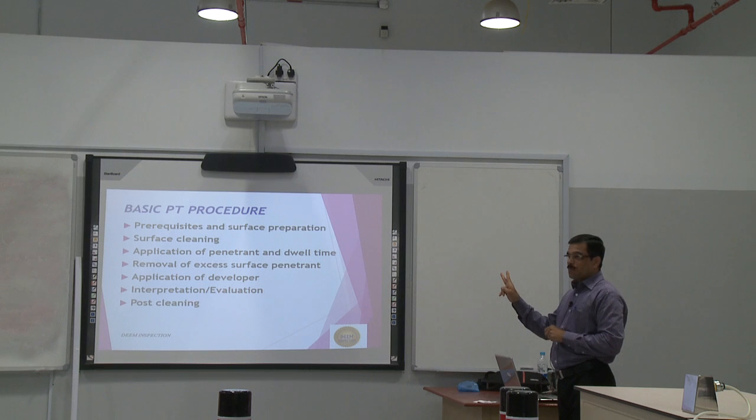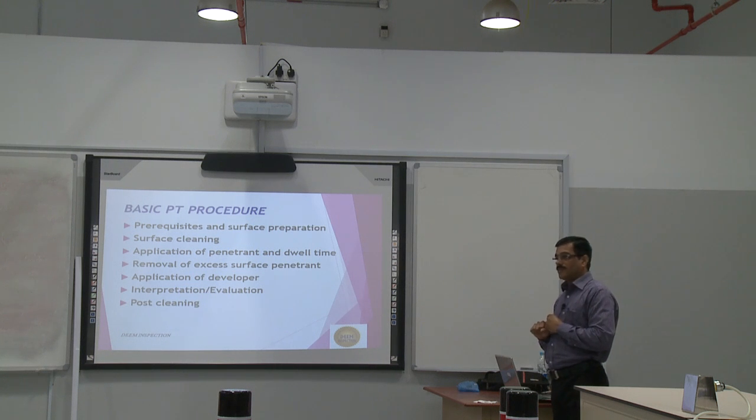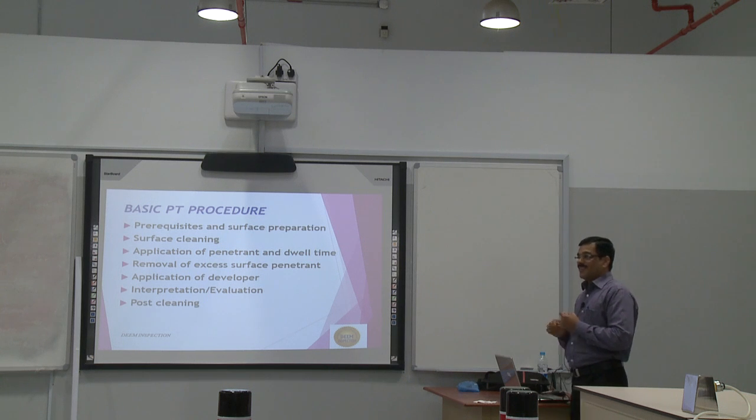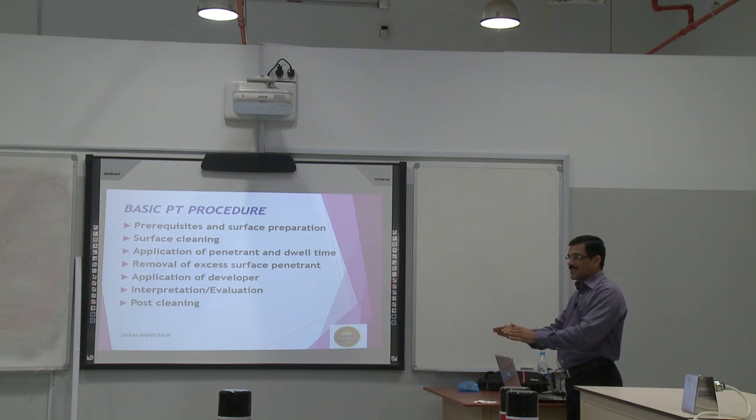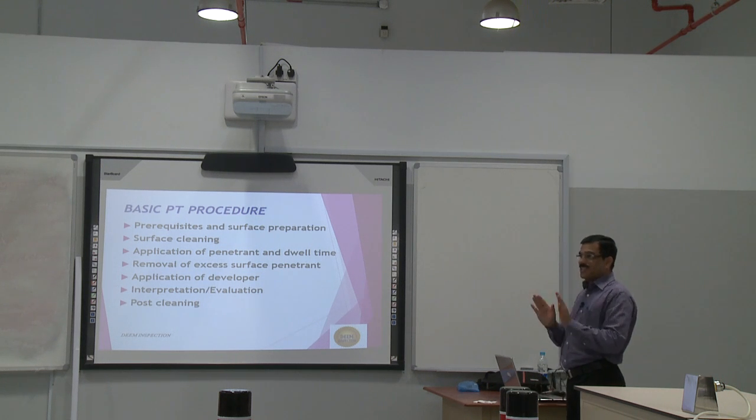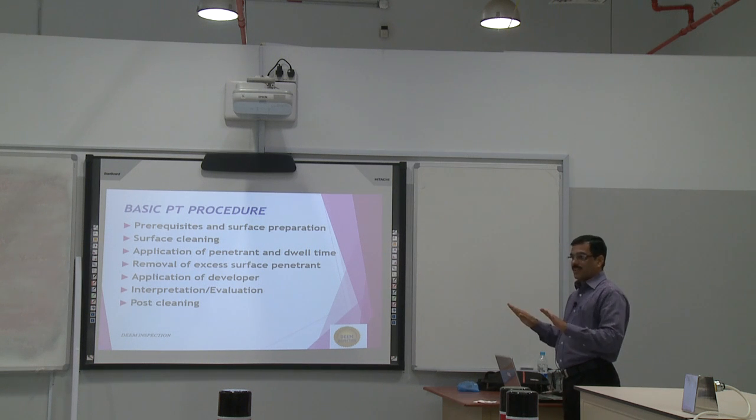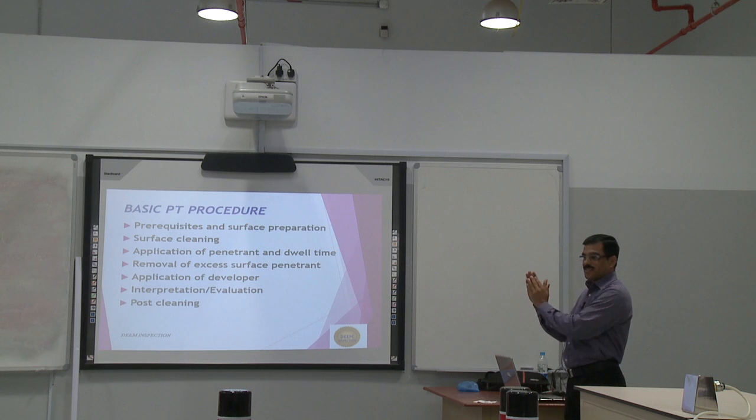So what is the difference between interpretation and evaluation? Any idea? Whatever you are watching, you interpret differently, based on your experience or based on your standard. Exactly. Evaluation means once you are identifying whether this is a defect or not. Exactly, you are right. Interpretation means we just say, oh, this is a crack, this is porosity. We are not saying defect, this is a discontinuity. But through evaluation, we are finalizing: as per this standard, this is rejected, this is accepted.